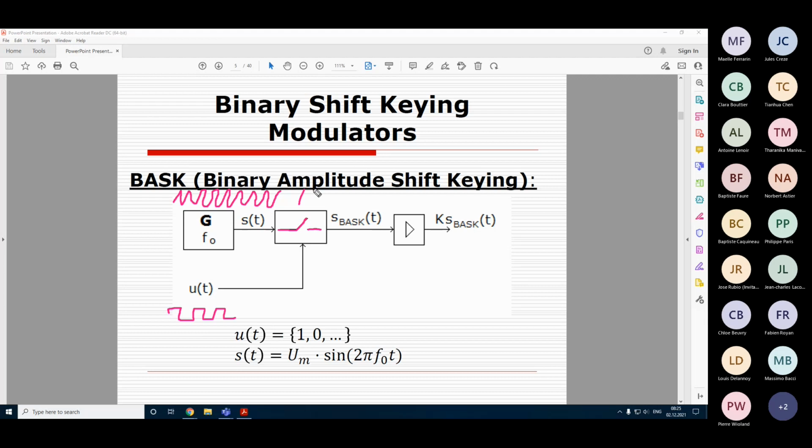You can use, for example, a transistor for this purpose, or rather, even better, a field transistor. Because bipolar transistors can also operate in cutoff mode: if the voltage exceeds a certain threshold, then it's open, otherwise it's closed. But it needs some resistors and so forth. And field transistors are actually more self-sufficient. We can use actually a single field transistor, and that's it, if we choose it correctly based on the voltage and so forth.